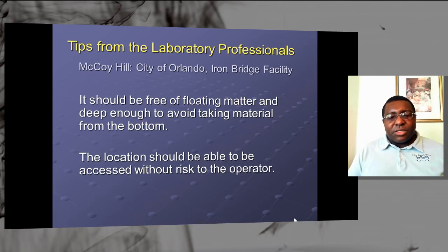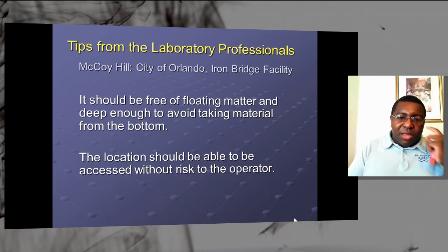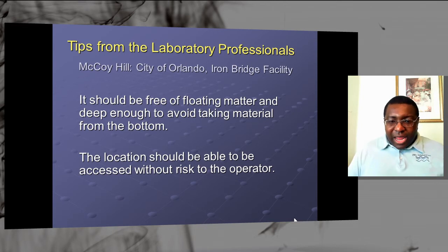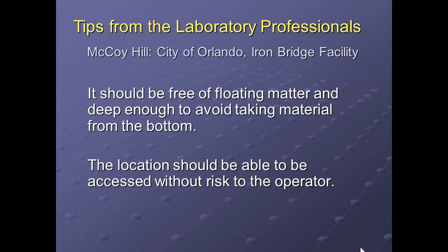I'll give you the last 2 that he has. It says it should be free of floating matter and deep enough to avoid taking material from the surface, but still avoid taking material from the bottom. So you're looking at middle of the tank, if at all possible, or at least a good 2 feet down.